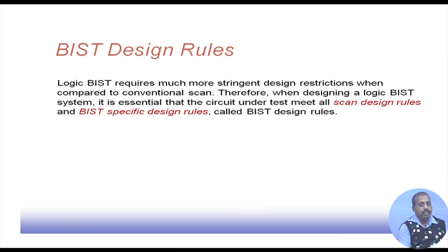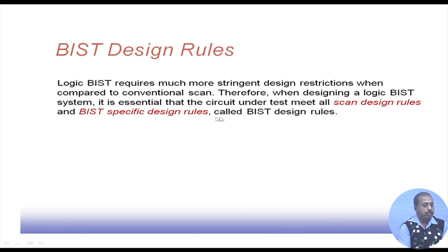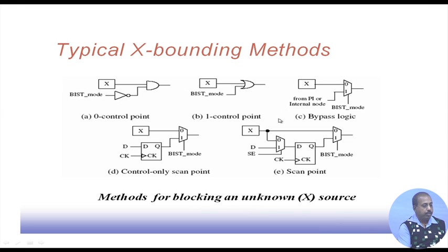The scan design rules must be satisfied because in most cases the test pattern generator generates bit streams to feed the scan chains of the circuit under test. Whatever scan based rules we have must be satisfied, and apart from that some more rules are to be satisfied. The scan design rules we have seen previously, so we have to look into these BIST specific design rules.